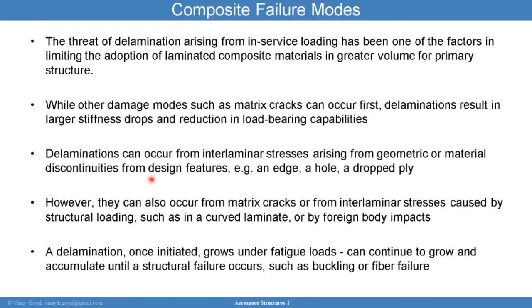Composite failure modes are quite significant and difficult to address in service. The threat of delamination that arises from in-service loading is one of the primary factors limiting the adoption of laminated composite materials in the greater volume of primary structures when it comes to aircraft.